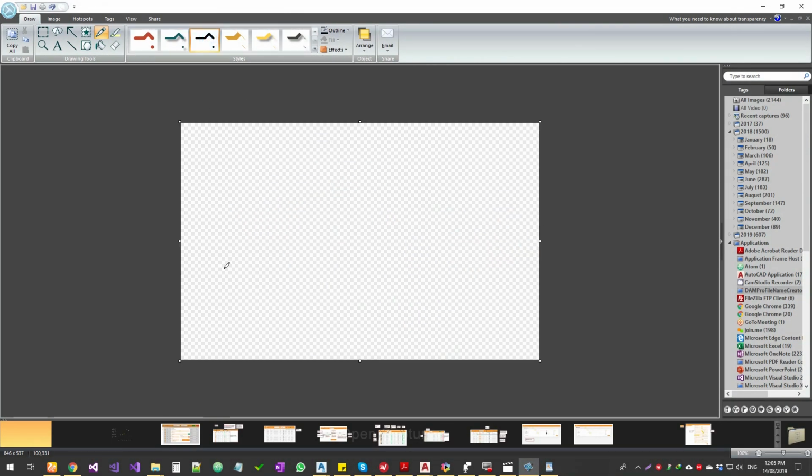Let's say we've got this road curving, and if you look at this road on this side, there is a little raise. This is your superelevation. So first we've got a 5% superelevation, and then 7% and 10%. You can have bigger superelevations.